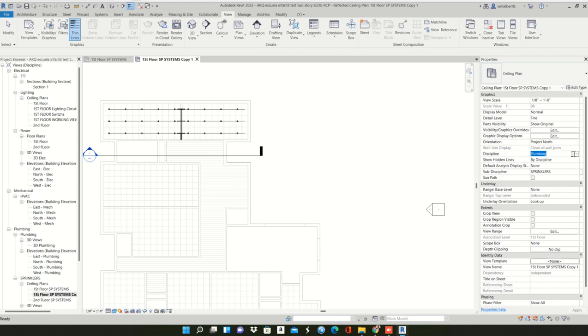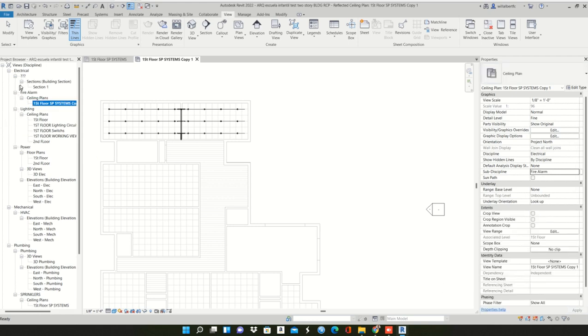The discipline is not going to be plumbing, because fire alarm is electrical, and the subdiscipline is going to be fire alarm. I will hit apply, and I see that I have a new discipline, fire alarm. Okay, I'm going to close the inactive views.